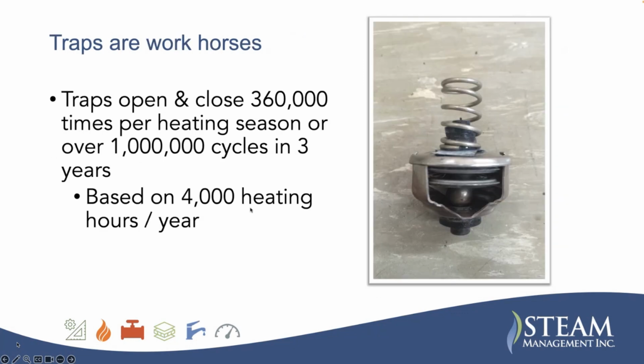Traps are workhorses. How long will they last? Well, a trap opens and closes about 360,000 times per heating season, or over 1 million cycles in 3 years. This is based upon 4,000 heating hours, which I have in my area. So, I see people that have them 20, 30 years old. A lot of times the new ones aren't going to last nearly that long.